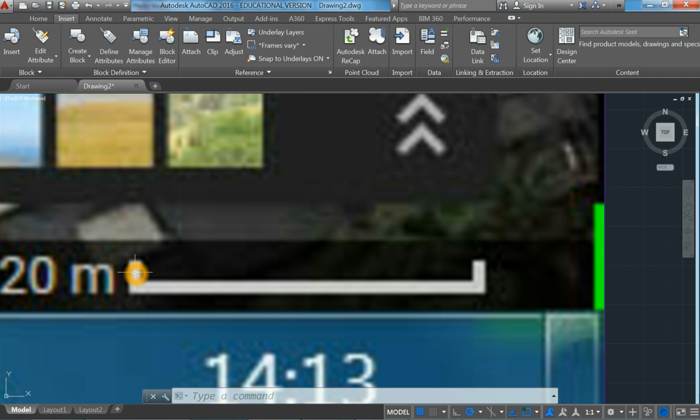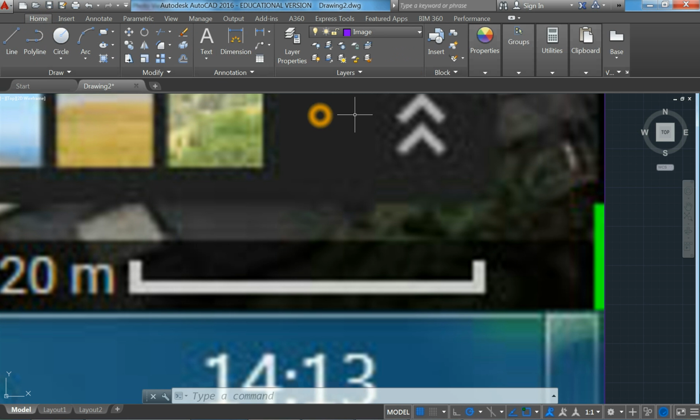But just be careful when you're measuring off a hand-drawn drawing, even if it's been scanned in, you might be measuring from the wrong point if you measure from the center. Because this is done digitally, I'm going to assume, and I usually do assume, that it's measuring center to center. But again, you never know, because you get some people working with computers who still have been trained the old way.